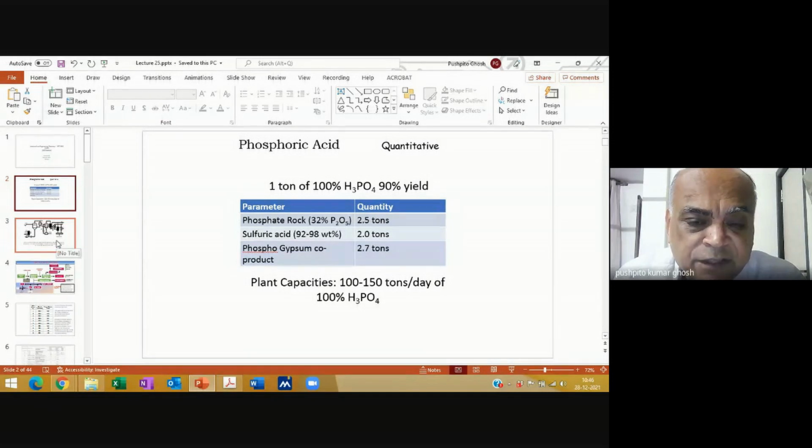Now, the second thing that you would have noticed, and I told you when we talked about the rock phosphate compositions from different places, is that all rock phosphate, except for chlorapatite, which is very sparse in availability, has about 3 to 4% of fluoride. And so the ideal thing is that the fluorine should be removed from the phosphoric acid before you produce fertilizer, because otherwise the fluoride will remain.